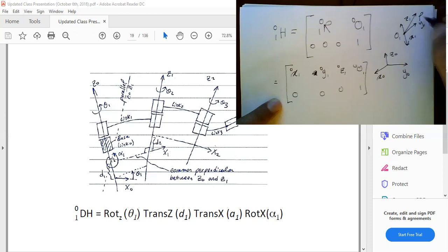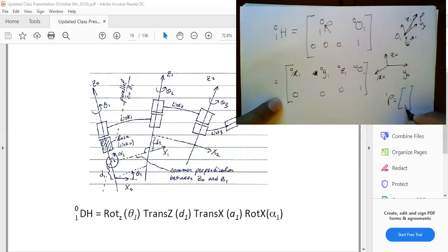If I ask you for p1, what is p1? You would look at your x1, y1, z1 for this vector p. And obviously we said this will always have a 1 at the end. If I multiply this by the transformation, I would get the coordinate of this tip in the base frame. But if I ask you to only perform rotation on this vector, you will put 0 instead of the 1. By doing so, you will get the projection of this vector into that frame.